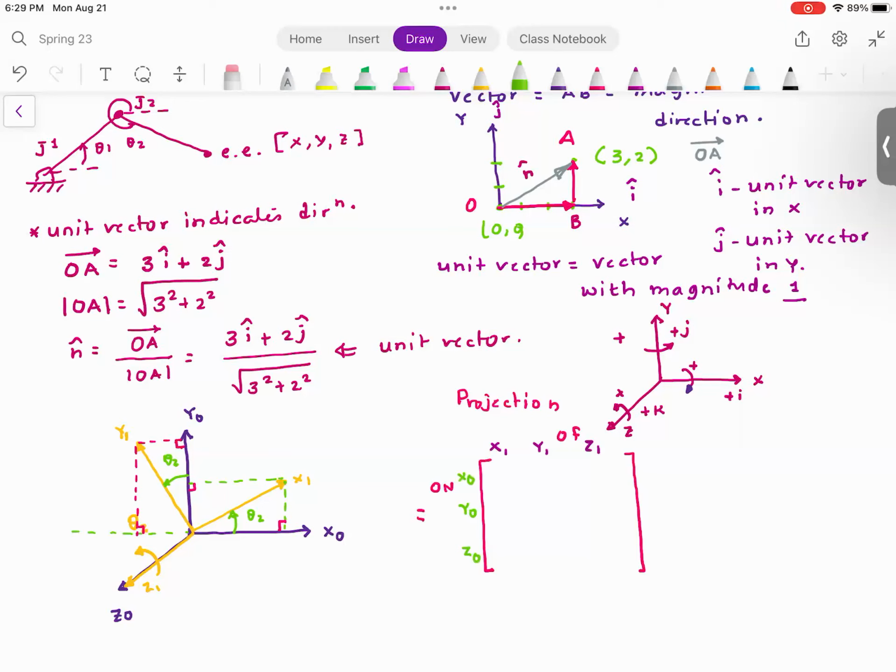And probably if you have studied projection matrices before, they basically draw projection matrices like unit vectors and find the transformation. But I want you to understand, you have your initial coordinate frame x0 and y0. You applied a rotation about z, so z0 and z1 are aligned. You applied the rotation, which means x0 went to x1, y0 went to y1. And I want to find out the rotation matrix between x1, y1, z1 and x0, y0, z0.